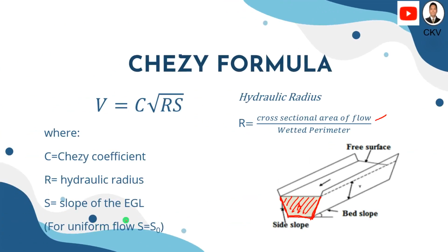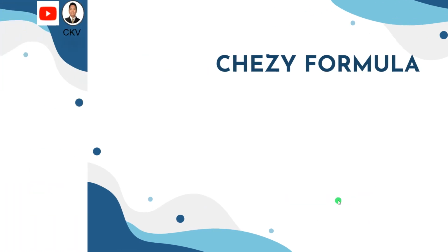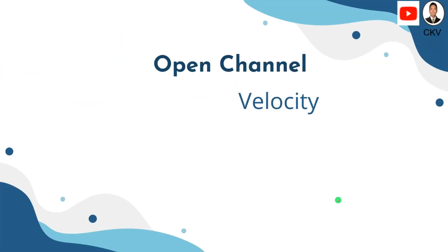While the slope of the energy grade line, if it is a uniform flow, means that the bed slope along this open channel will be your equivalent slope. Okay, but if it is not uniform, we will refer to the energy grade line for the equivalent slope.